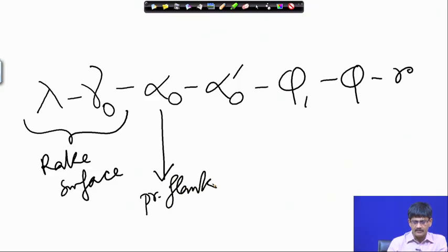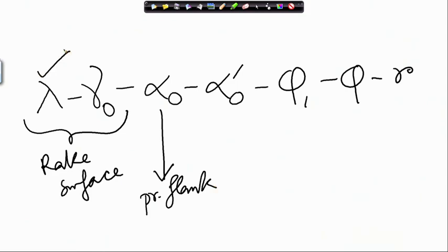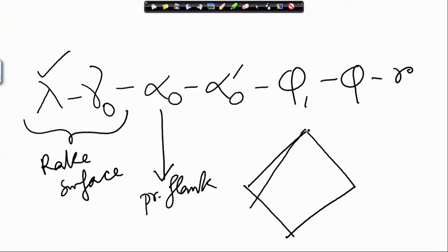You might say, can the principal flank be defined completely this way? Just a single angle is there. Well, some information is going to come from this one. Okay. For example, with these, suppose I define the rake surface with these two, and on that I define the principal cutting edge.